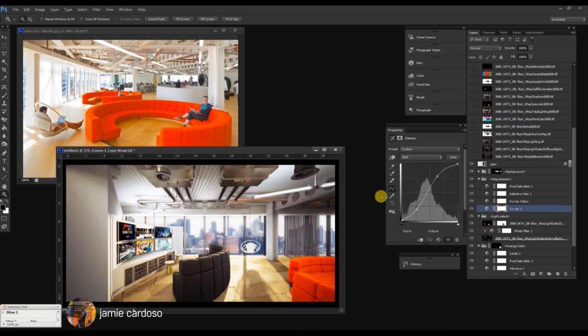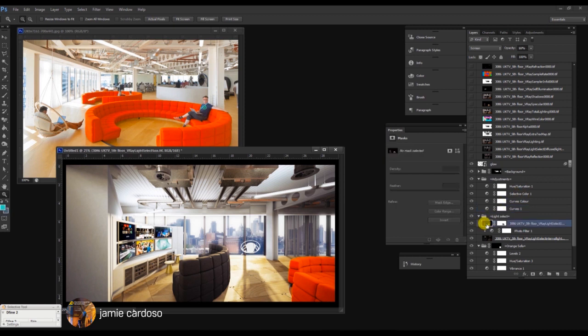So this is why. Every time you want to use the mask, you need to ensure that you're clicking on the mask there, because if you click in here, you're actually selecting the layer as opposed to the mask. So by accident, you can just start. See there. You don't want to be doing that. Control Z to go back. So every time you want to mask something out, you have to make sure that you have the mask turned on there.